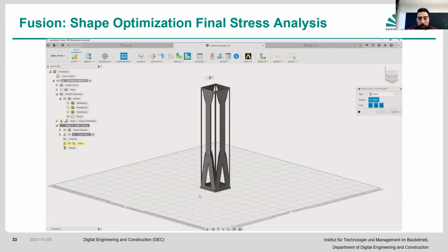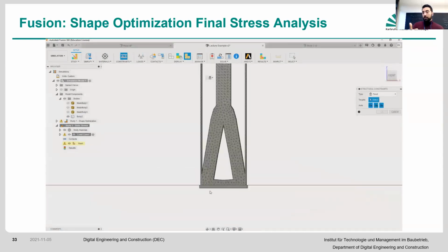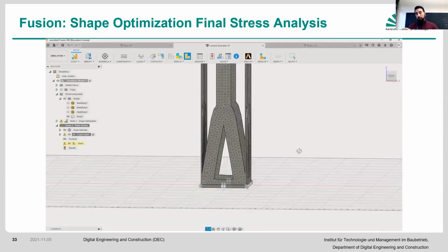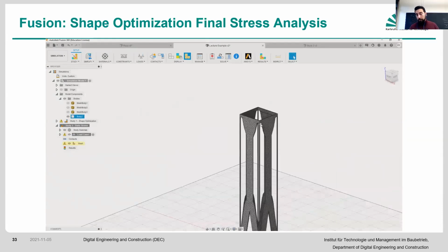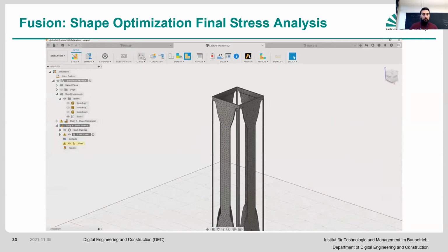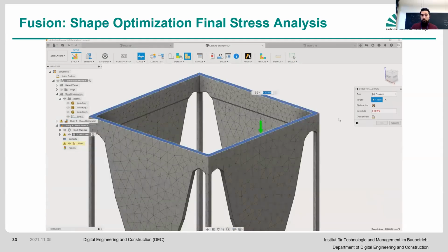This is where, of course, you do the exact same thing. So with the static simulation, you need to again provide the constraints. You have to create another nice area there, because that was not a part of the optimized shape. We basically constrain that there on the bottom. We add the load on the top, again, a pressure load, which is a static force.